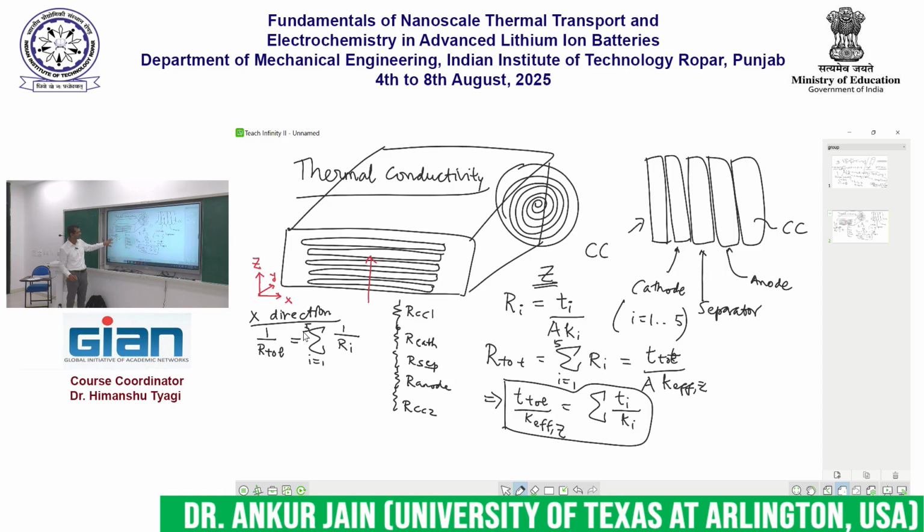Instead of the previous expression, it becomes a little more complicated, but from here, R total is L over AK, so K effective in the X direction times T total will be equal to summation Ki Ti.